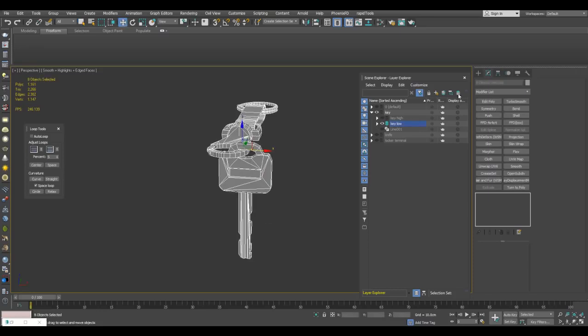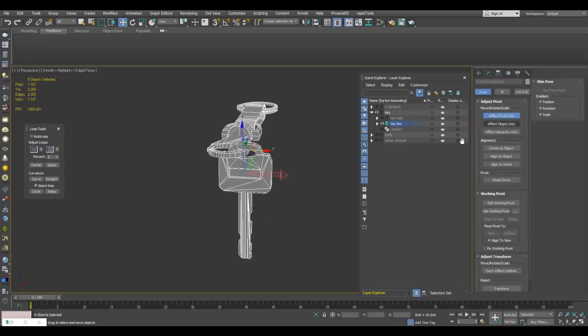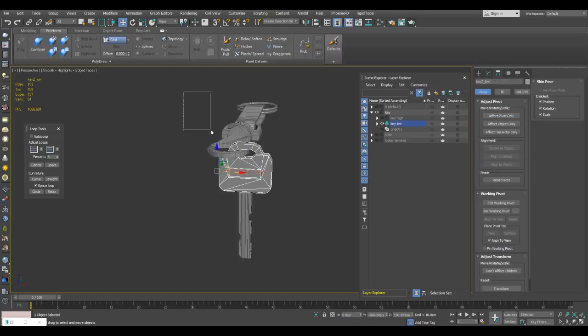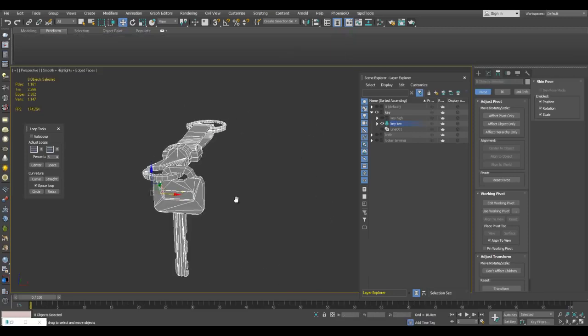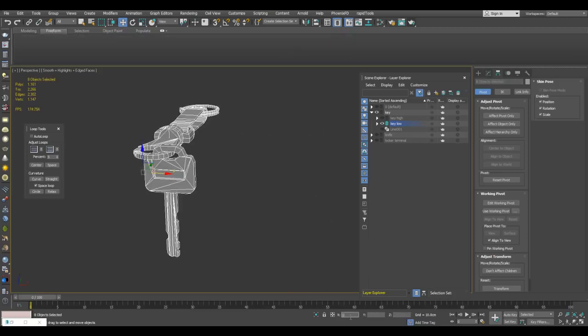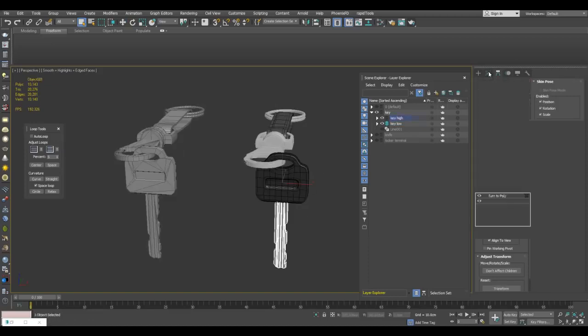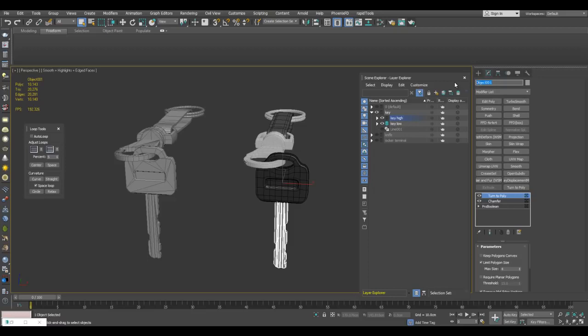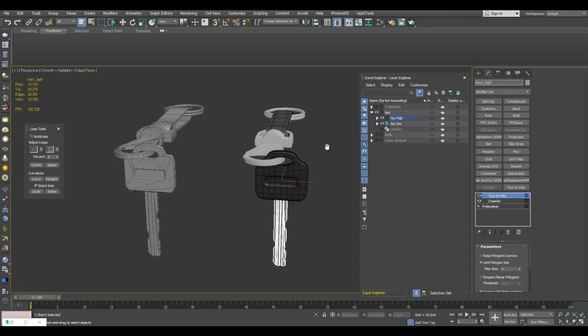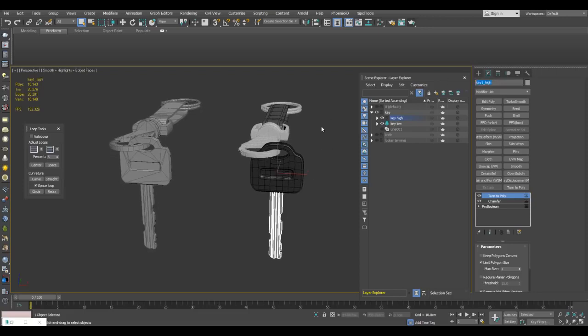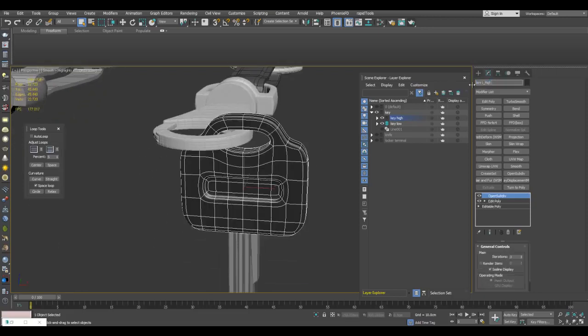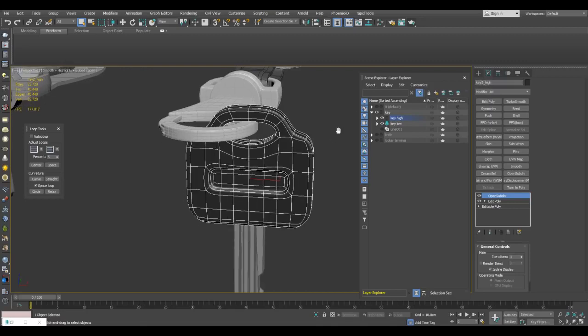Now what I can do real quick here, just select these objects, go into hierarchy, pivot only, and make the pivot be 0 on the x-axis. The reason for this is because now with the pivot at 0, what I can do is simply move all of this, and to return it back to 0, I can just enter in 0 right here. So I'll do the same thing for the names, except this time I'll call it key 1 underscore high. I can just Control C to copy this, go down here and just change a single number here.